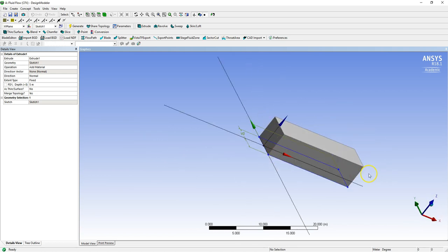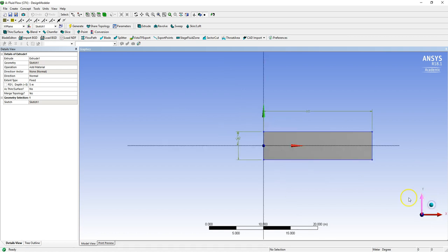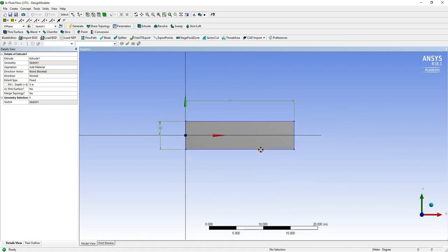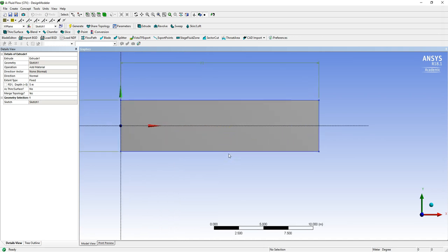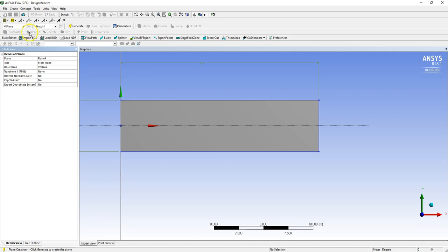Flow is going to come in this end and out the other. So the next thing to do is create a flat plate that's opposing the wind about 5 meters into the case. So just selecting Z, holding down Control, holding down middle mouse button and just dragging along, scrolling in with the middle mouse button. And what I want to do is create a new plane in the X and Y, but I want it to be slightly elevated from the ground. So I'm going to transform that, and I'm going to offset it by the global Z coordinate.